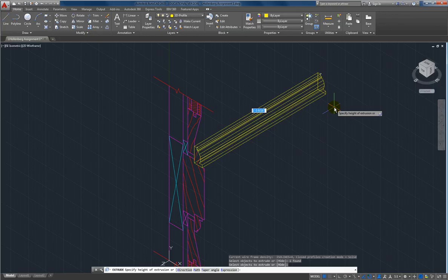So you might want to pick a standard extrusion. So this is where you got to get smart. The move command is going to be critical. What I'm going to default to is I want to take, say, a 2-foot section. So I want 2 feet of this. So my extrusion from one end to the other will be 2 feet.